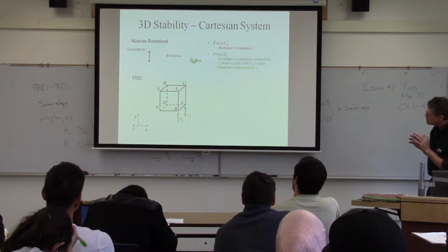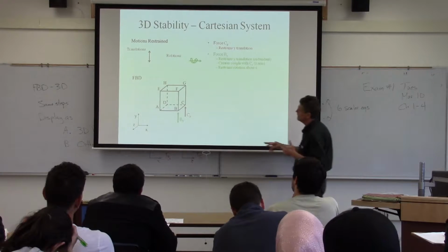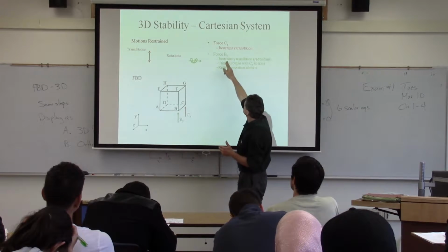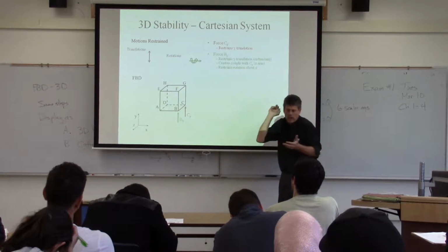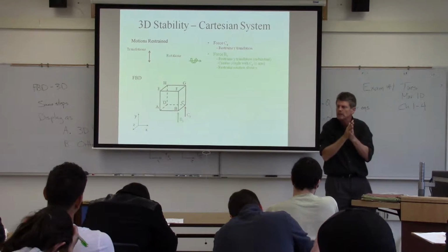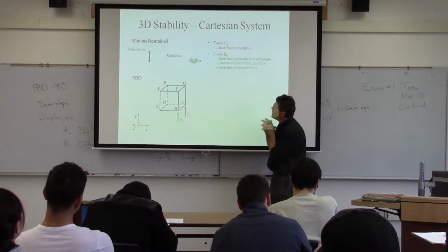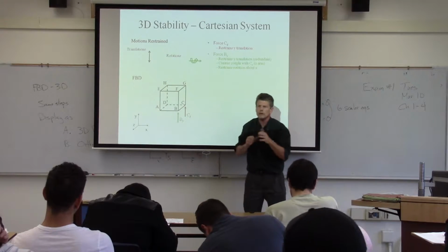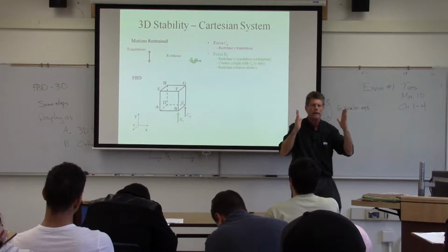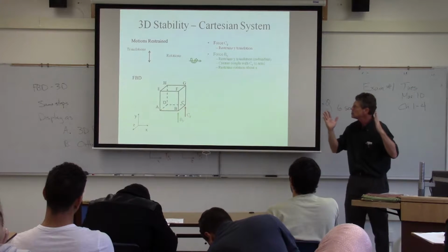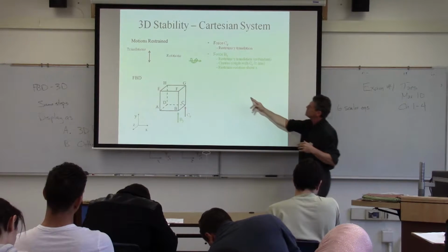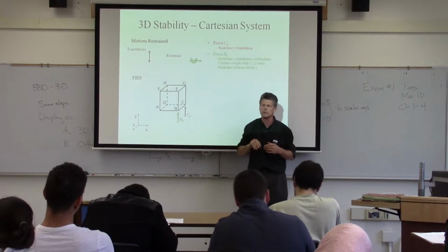Now, if I add the next piece, B, well, it's in the same direction there. So in terms of restraining y translation, it's redundant. It's doing the same thing. We might want redundancy, especially if we're civil engineers. But the other thing, too, is now that I've got two forces that are out of line of action there, I have the ability to create a couple to resist any sort of rotation.